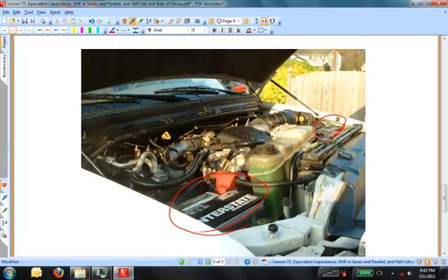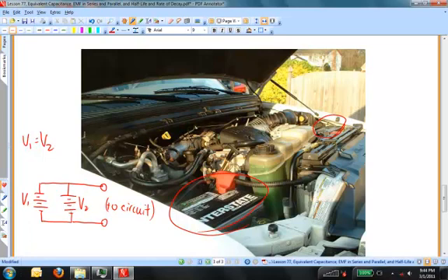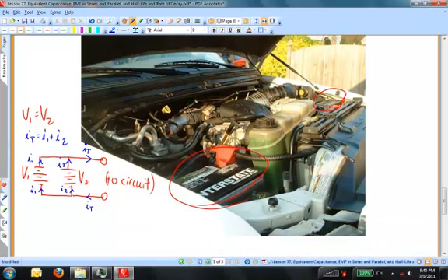Generally, batteries connected in parallel will have equivalent voltages, like the two 12-volt batteries under the hood of a car. It really makes no sense to put batteries of different voltages in parallel with each other. So, the voltage drop across parallel batteries will usually be the same. On the other hand, the current that's supplied by the network of these batteries is going to be equal to the sums of the current supplied by each battery. Both the batteries serve as charge pumps, and they boost the ability of the network to deliver current to the device requiring it. And now for batteries in series.